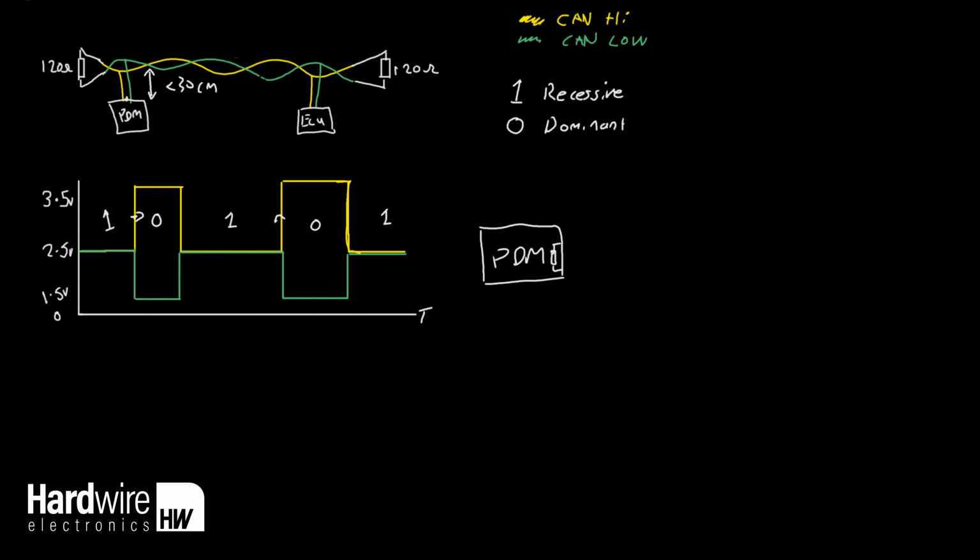And so there's absolutely nothing wrong with having your CAN bus like this going to another device like your ECU. There's nothing wrong with that. You know, you might have your internal resistor here, or indeed if you're not using an internal resistor, you might have to add one on the outside of the bus here as well. Ultimately, you just need to make sure that the resistors are close to, if not at the very end of, the CAN bus like this.